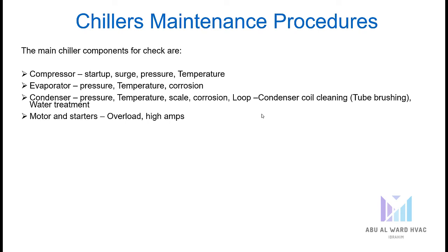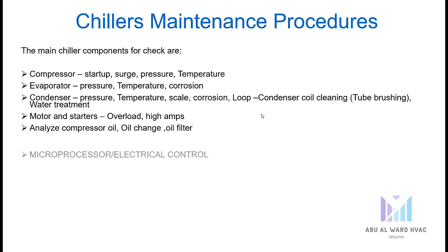Motor and starters, we need to check if there is overload or high amps. We need to analyze the compressor oil annually. We need to change the oil as well as the oil filter.